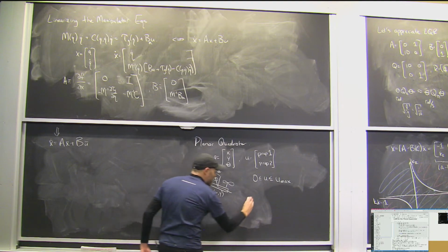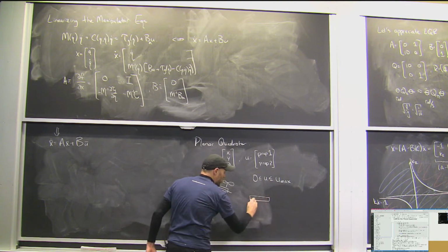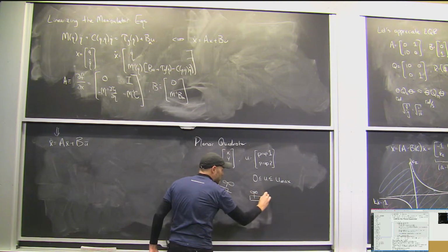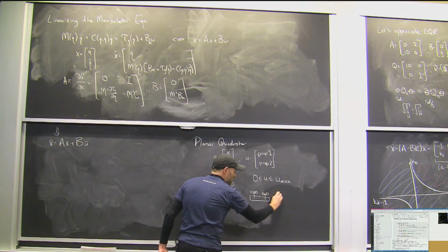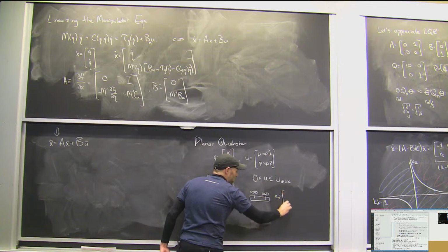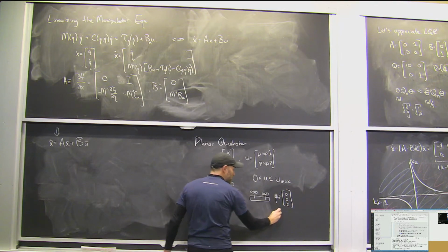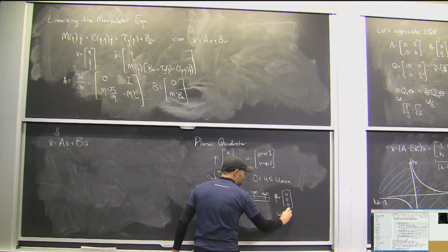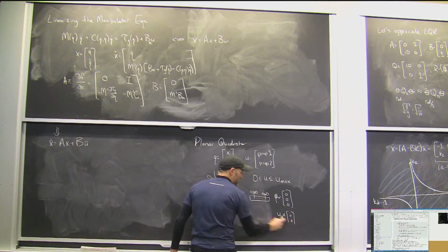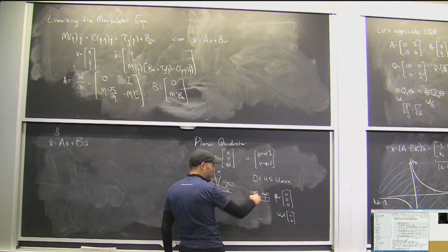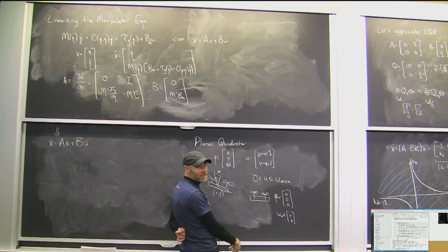This one is interesting because to find a fixed point to stabilize around, Q0 even could be 0, 0, 0. I'm happy with that. But U0 can't be 0, 0. If I've got no thrust coming, my quadrotor's falling out of the sky.